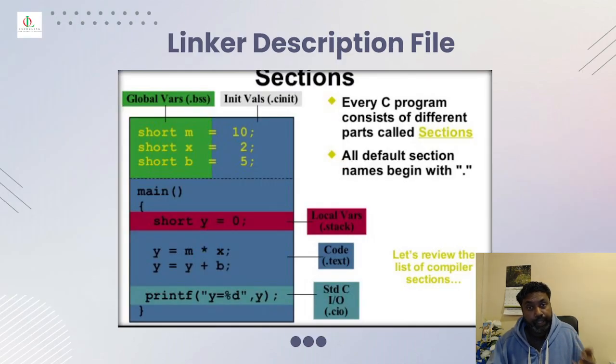I talked about the linker briefly, I think on day 2. So this is where I'm going to give you more explanation about the linker. When you work on a major project, like a complex project, the default linker will be by default connected to the external memory, just to avoid congestion on the main microcontroller memory. So it will be added to the external memory to do multiple complex things.